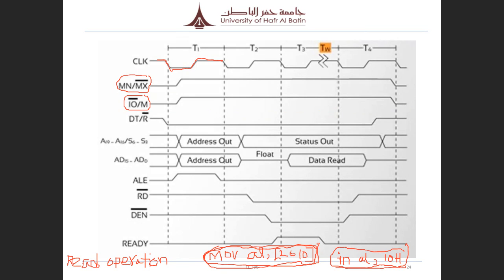Then data transfer or receiver. During the read operation, data is coming to the microprocessor. That means the microprocessor is in receiver mode, and for receiver it is a bar. That's why it becomes low throughout the time. It becomes low until you finish T4. Okay, it's like that.